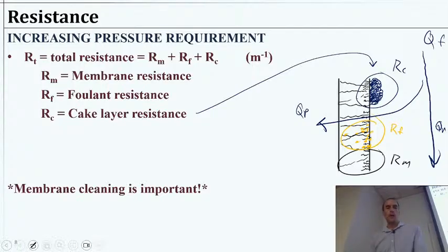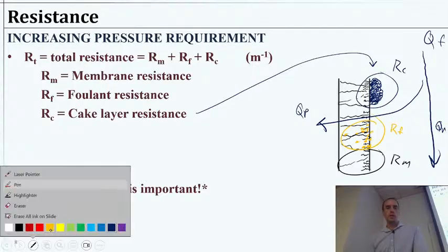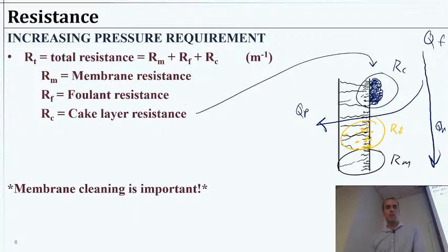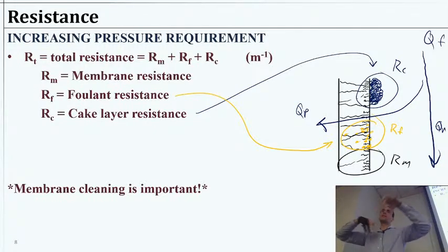There's another type of fouling, just generic fouling, I guess, that we could describe as particles that are getting stuck kind of in process. So along the way on any part of the pores, inside the membrane, on the pores, not the cake, but just adding texture and slowly constricting the pores. So these are all this stuff here, kind of on the inside. That's what we're talking about.